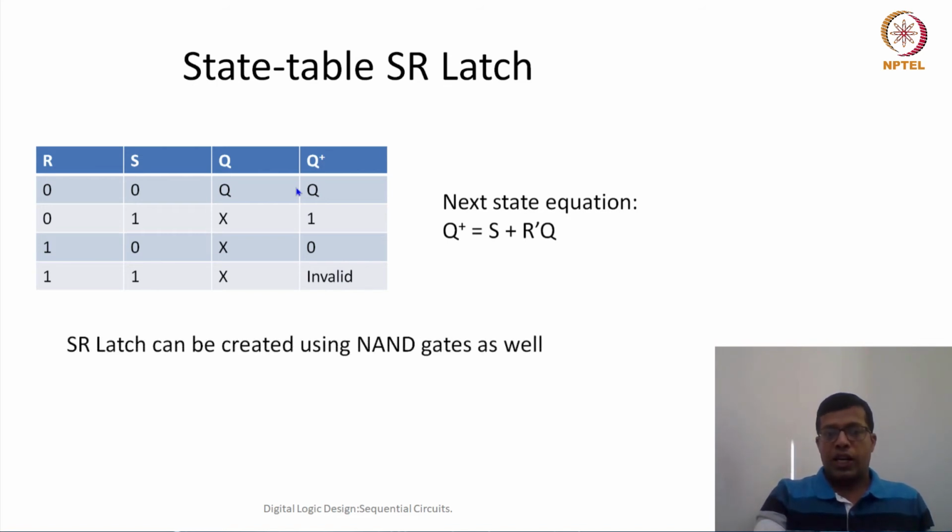As I have said before, this RS latch can be created using NAND gates also, but in the case of NAND gates, this state table would change a little bit because of the inherent nature of the NAND gate. You can take it as an exercise to create an SR latch using NAND gates.